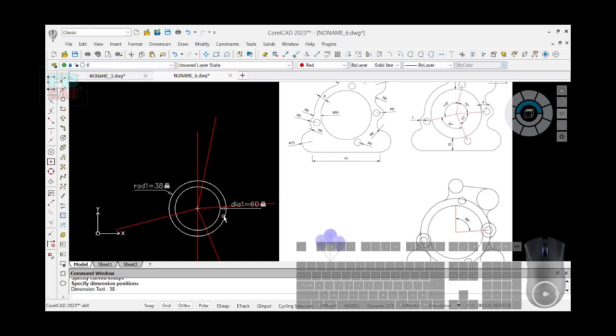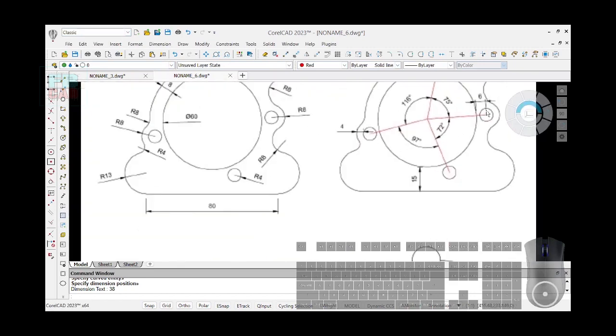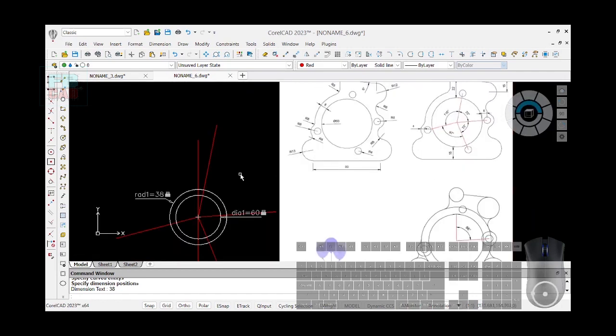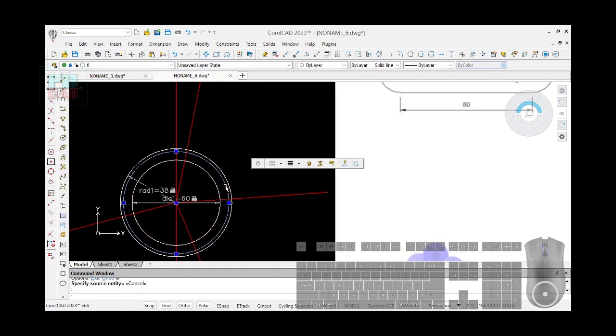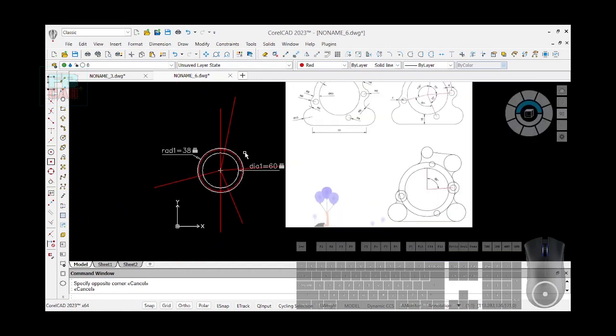Now, if you look at it, we have under offset here to the center of this smaller circle of radius 4. The circle is radius 4 and it's 6. So we're going to offset the same by 6. Good. We've offset it by 6, and that should be a construction line. So construction circle, just a guide. So we have it there that way.